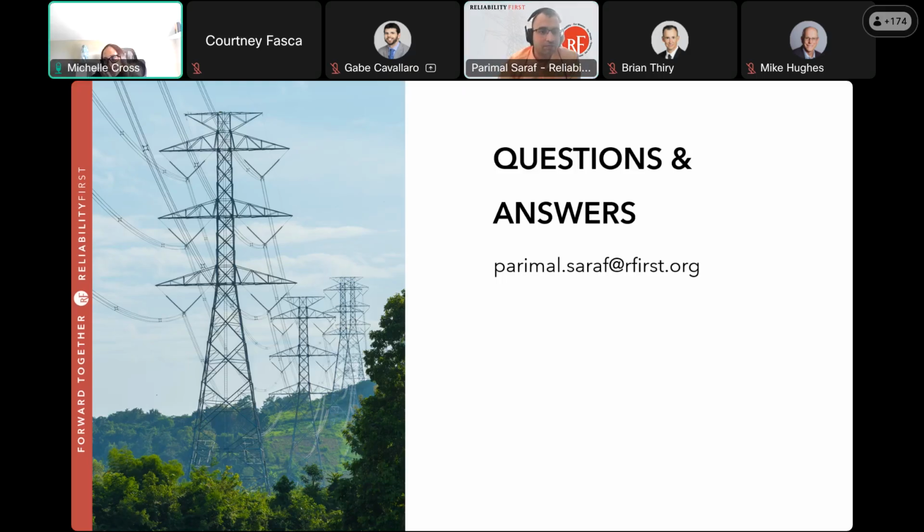Okay, great. The next question, I'm going to combine two questions because you had some questions on the synthetic inertia, and you talked about this a little bit in your final slides when you were talking about grid forming inverters, which could make synthetic inertia possible with IBRs, right? Yes. So the question is, what did you mean when these IBRs can emulate inertial response but require active power headroom to do so? If you could elaborate a little bit on that.